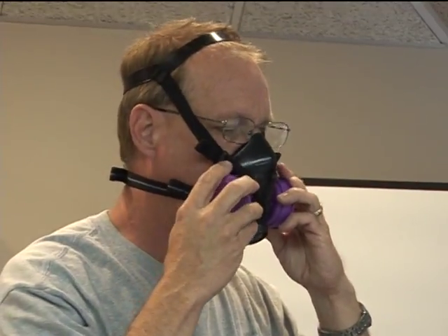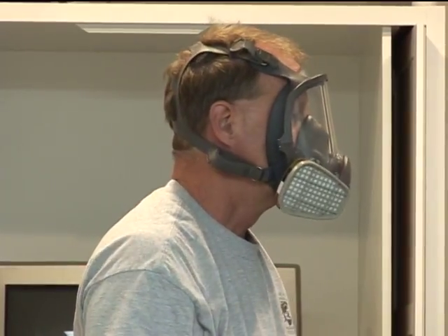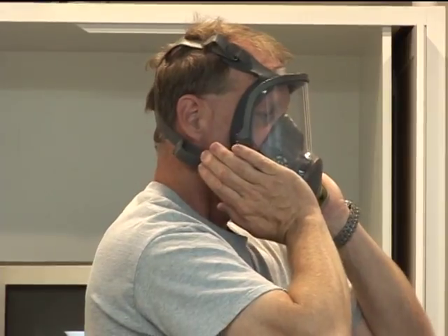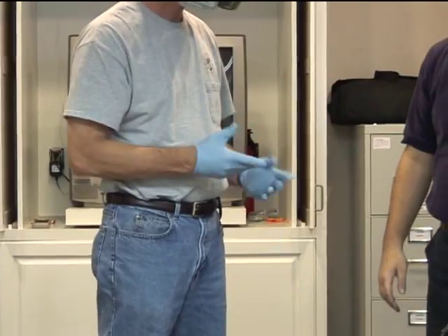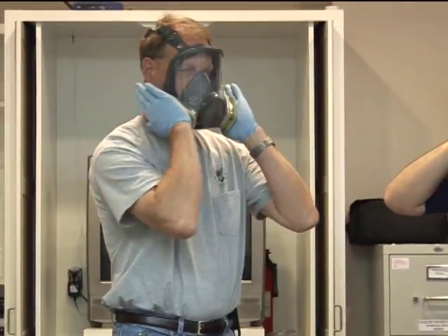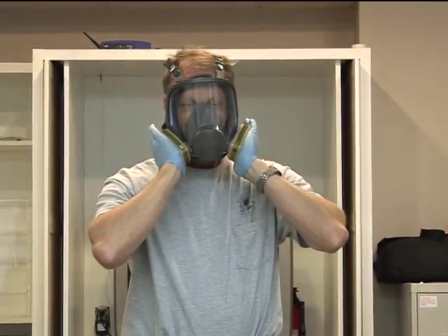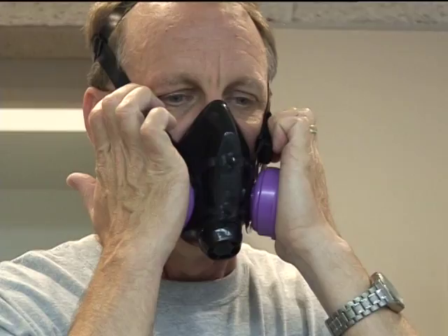A negative pressure check is performed by closing off the inlet opening of the canister or cartridges by covering with the palm of the hands or by replacing the filter seals, inhaling gently so the facepiece collapses slightly, and holding your breath for 10 seconds. The design of the inlet opening of some cartridges cannot be effectively covered with the palm of the hand. The test can also be performed by covering the inlet opening of the cartridge with a thin latex or nitrile glove. If the facepiece remains in its slightly collapsed condition and no inward leakage of air is detected, the tightness of the respirator is considered satisfactory.